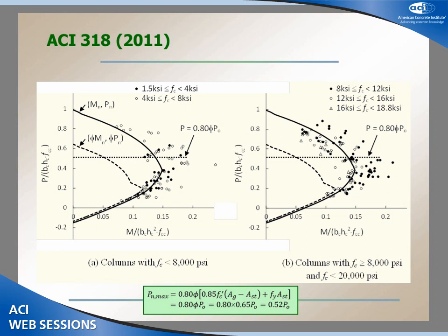If you look at plot A, you can find that even for normal strength concrete, at some data points the code still overpredicts their strength. So this overprediction applies not only to high strength concrete, but also to normal strength concrete. But knowing that the code also has a reduction factor, we can see that large safety margins are maintained throughout all the data points, regardless of whether they are overpredicted or not. And the amount of overprediction is very small.